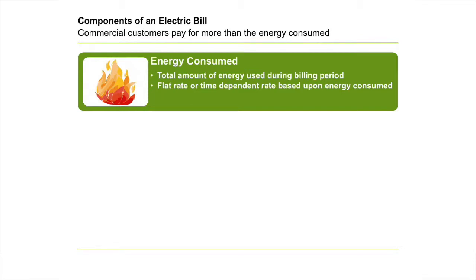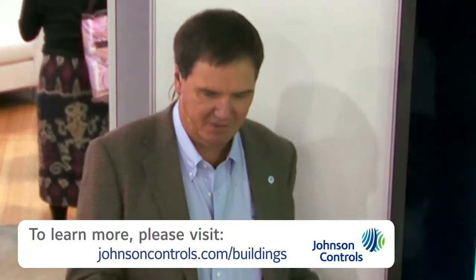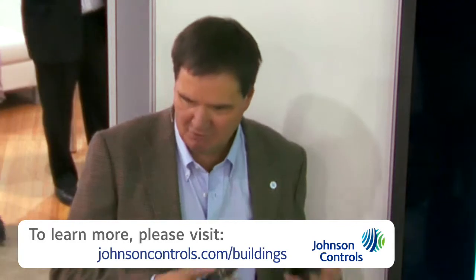There's typically two types of rates that are applied to this type of system. The first would be a standard charge rate where it's fixed throughout time. So it's 20 cents per kilowatt hour, for example, for as much energy as consumed. The second way that it's done is what's called time variable rates, where the rates change based upon the time of day. If it's difficult for utilities to maintain electricity, rates go up. If it becomes easier for them to maintain electricity, rates go down. And in a commercial building, you would typically see rates be high during the day, and then low in the evening.